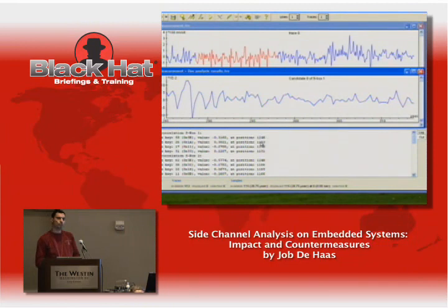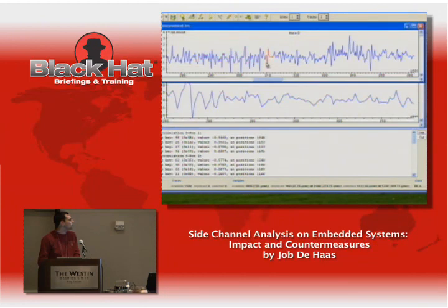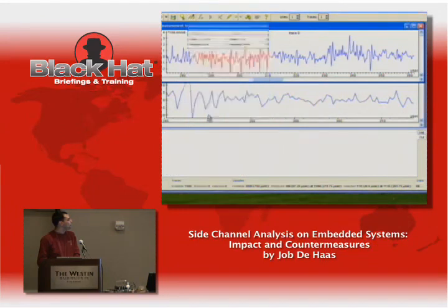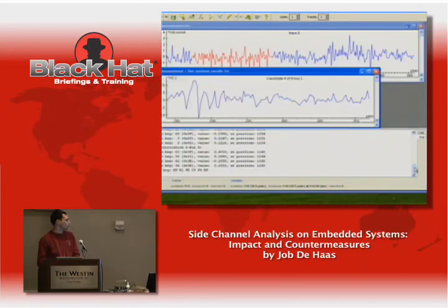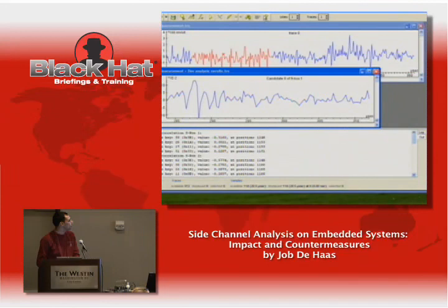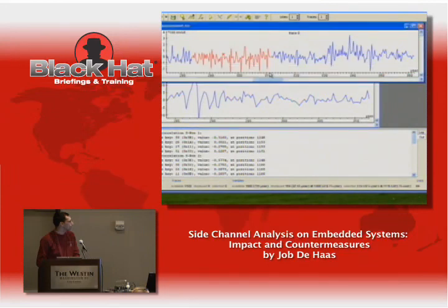because I can see the position where the best correlation was for this S box, and actually the best ones should be all in the same position, because I know it's calculated at that point. So actually what I'm going to do is take a little bit less of the output and run it again to see if I get a better result there. So back up. No, I was still not at a good position. Let me check.